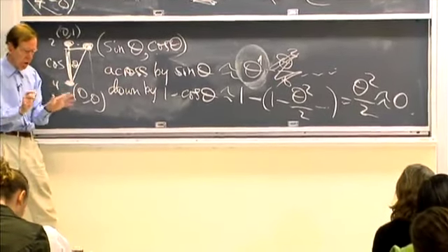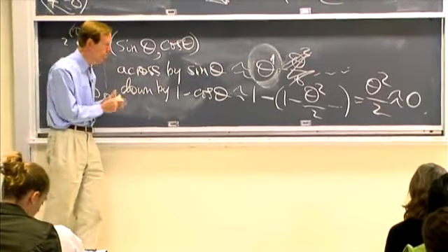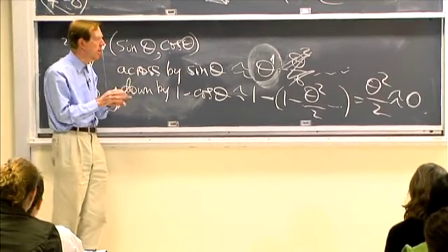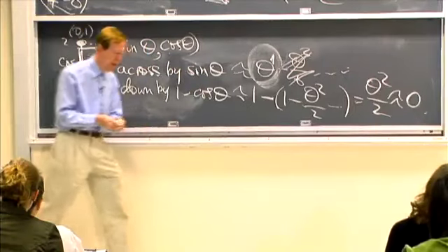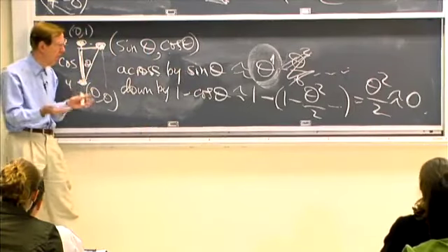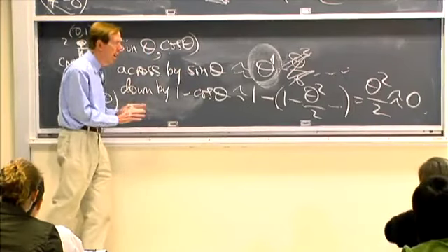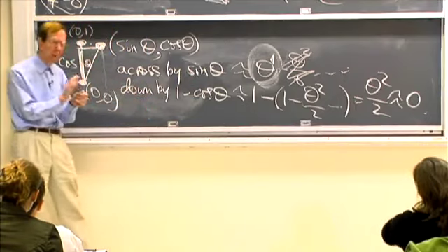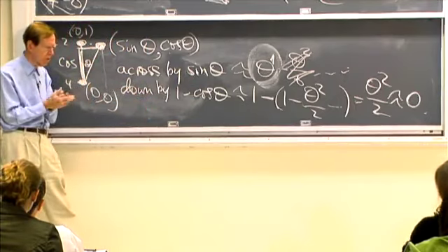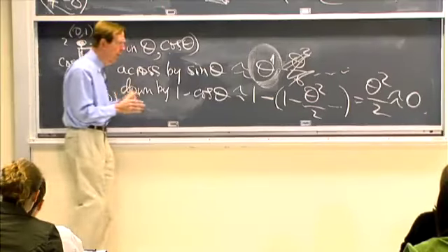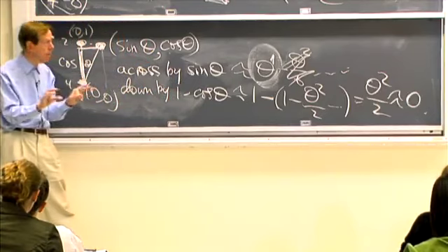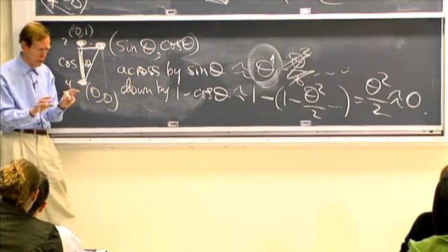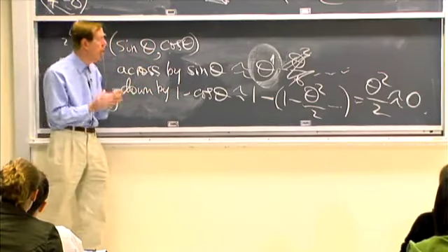If theta is small, as I'm going to assume, small displacements, then if I allowed theta squared and cos theta in here, I'd have a nonlinear problem. And I don't want that, and I don't need it. I mean, finite elements, structures, bridges, whatever, your first hope and expectation and calculation is small theta, linear problem.